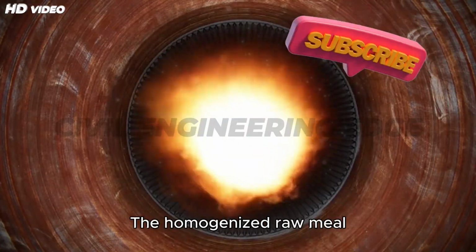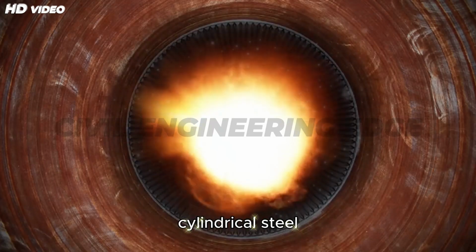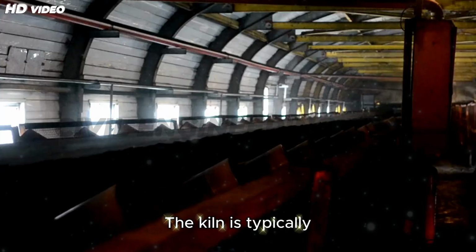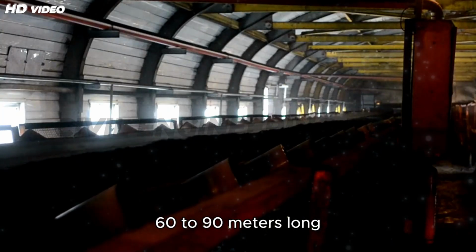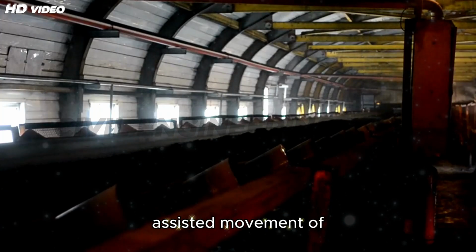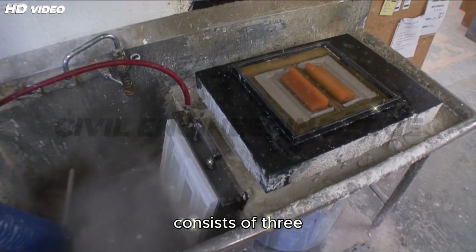2. Heating in a kiln. The homogenized raw meal now enters the rotary kiln, a massive, cylindrical steel structure lined with heat-resistant bricks. The kiln is typically 60 to 90 meters long and slightly inclined to allow gravity-assisted movement of the material. The kiln process consists of 3 thermal zones.